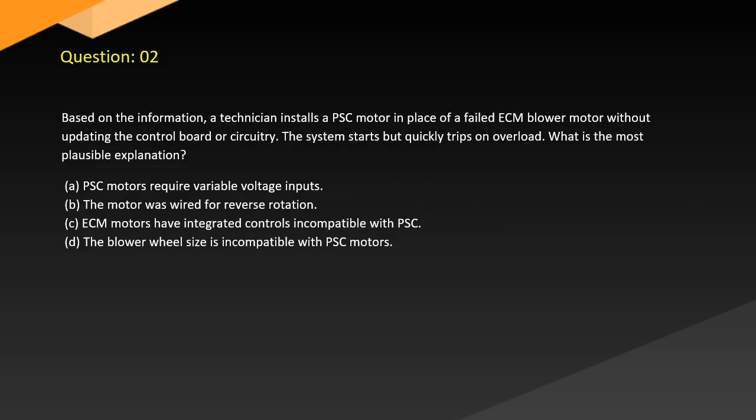Question 2. Based on the information, a technician installs a PSC motor in place of a failed ECM blower motor without updating the control board or circuitry. The system starts but quickly trips on overload. What is the most plausible explanation?